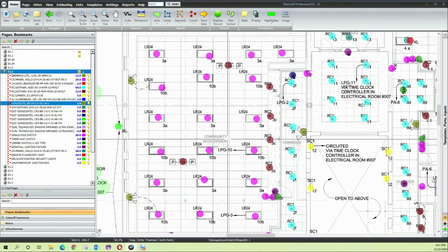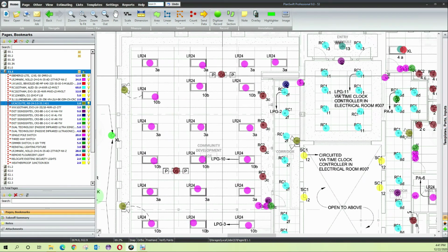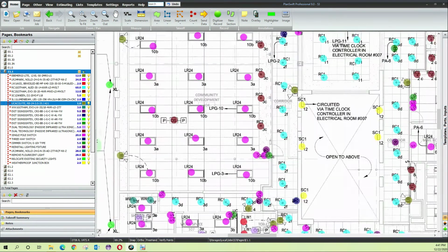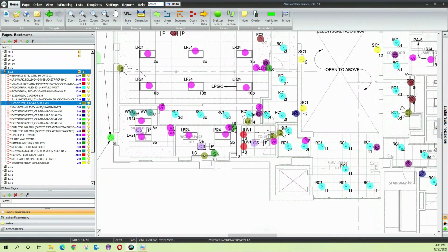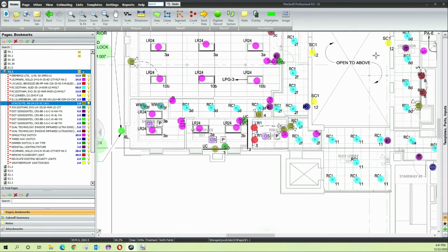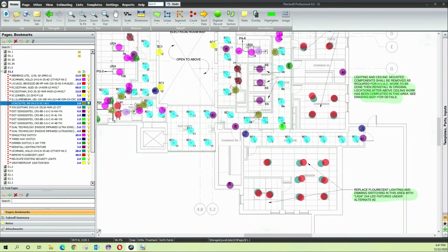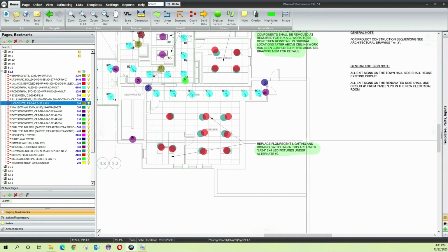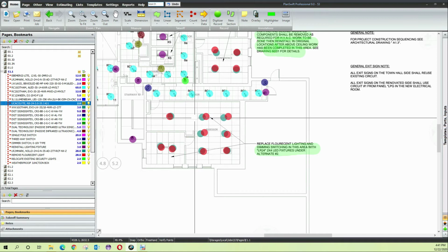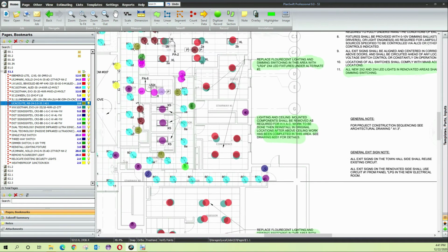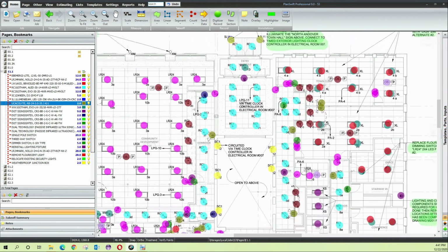So we have completed the lighting fixture takeoff for the first floor. Here you can see that I've counted all the lighting control equipment, like these occupancy sensors with the associated power packs, and all the light switches. This is the light you see. I will count that in, and you can see that I have counted all these removals of the fluorescent light with the LR24 lighting fixture in the alternate number 2 lighting folder, and so we are done with it.